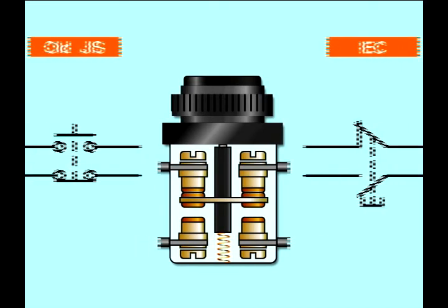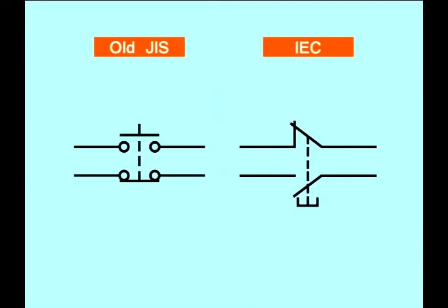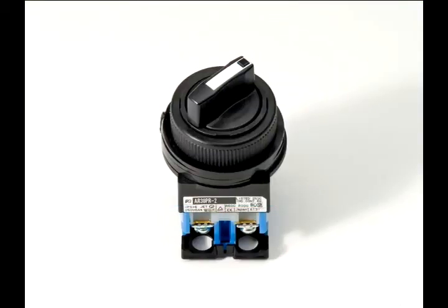The A contactor closes and B contactor opens when the C contact push button switch is pressed, and they return to their original states when the button is no longer being pressed. Shown here is a turnover switch, a C contact with residual function.